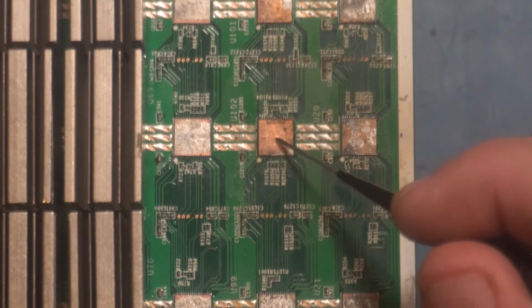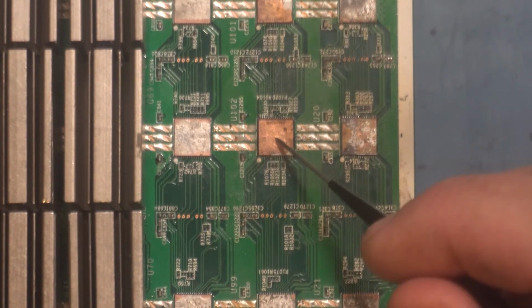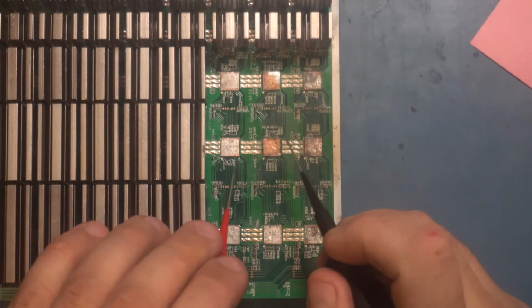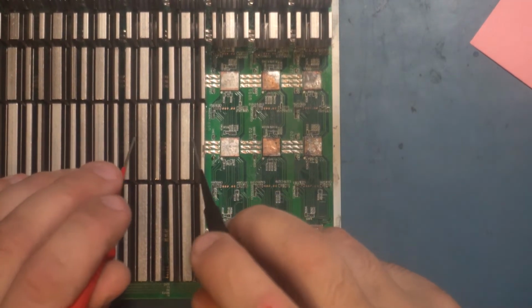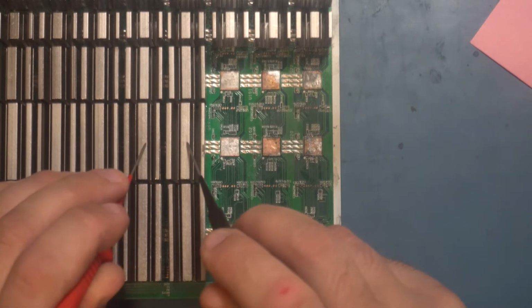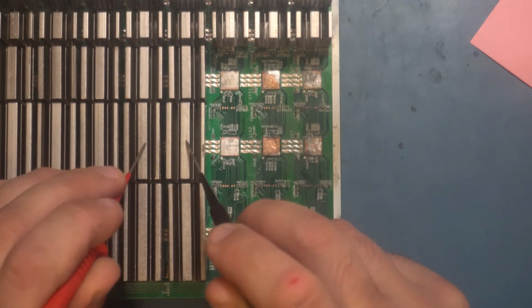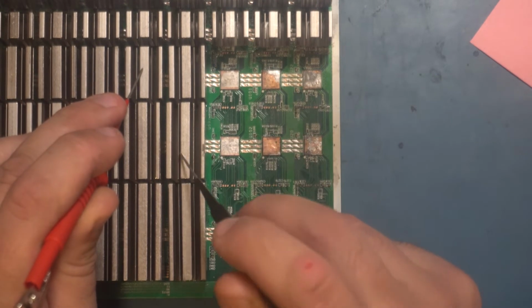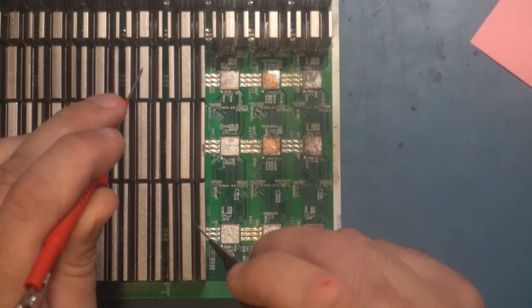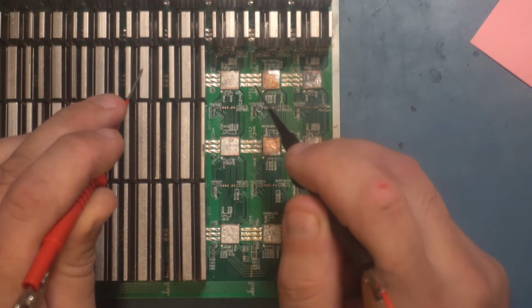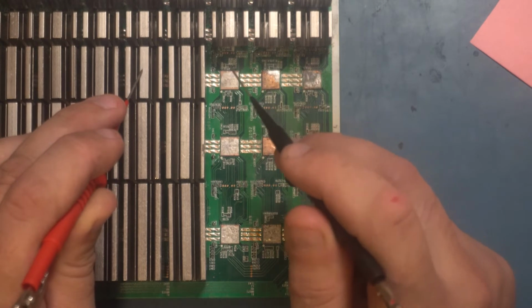And so what you can do when that happens is, if I measure from heatsink to heatsink here, and I don't have a result, or I get some weird floating value, then I can try a different set of heatsinks, or any combination. All of those in theory would be connected to the same ground, because all the chips on the same domain have the same ground, because they're all in parallel.